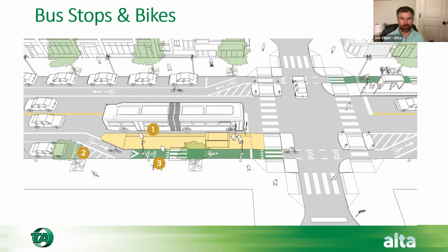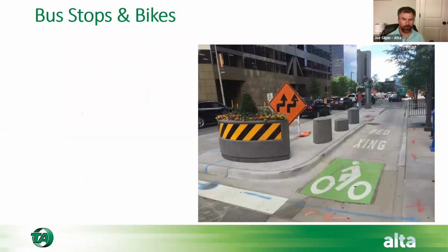It's really beautiful in some ways, but it shows how this conflict can be negotiated really, really well. So here's the bicyclists remerging into traffic, and these images were from the NACTO Transit Street Design Guide. Here's an example from Denver where they're doing the same thing, and here the bicyclists are merging back into their bike lane on the far side here. It's hard to see, but they're coming back in. I have dozens and dozens of pictures of floating transit stops in cities all over the country.